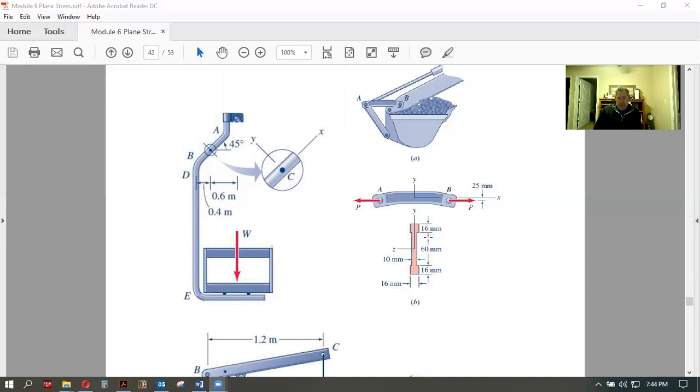The little front end loader assembly that you see here on the right, it's kind of interesting. We've got this little link AB there, and you learned how to analyze these systems back in statics. They were pin connected systems. You learned typically how to model trusses, and then you went into machines and frames, and this would be one of the typical kinds of machines problems. The little bracket AB is different than what you might have seen back there, and that is that although there could be, and certainly is, a straight line you could draw from A to B on that linkage, the thing is the actual mechanical piece is not a straight line.